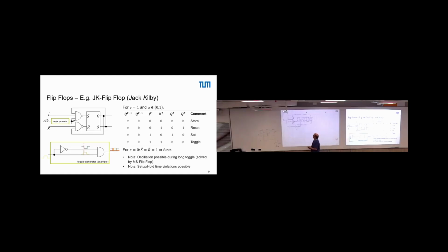Okay. Now let's see what happens if we are in the time phase where we operate the first half, and we have J and K, let's say, both at 1. No, 1 and 0. Yeah? So if this is 1 and 0, the output from this here will be a 1. And then if you look it up before, its reset bar is 1.